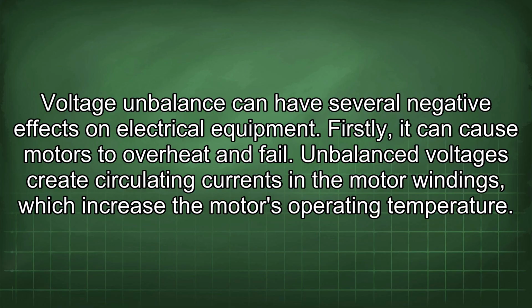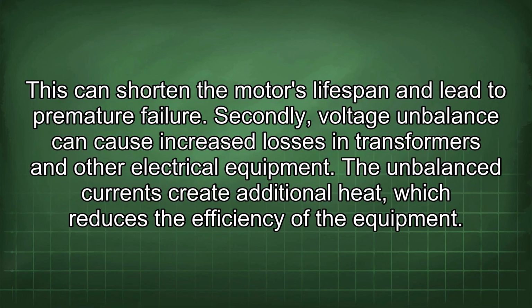Firstly, it can cause motors to overheat and fail. Unbalanced voltages create circulating currents in the motor windings, which increase the motor's operating temperature. This can shorten the motor's lifespan and lead to premature failure.